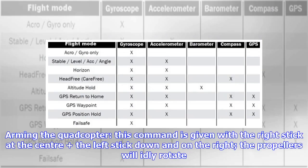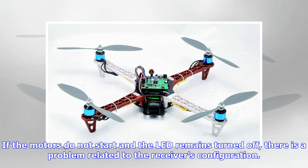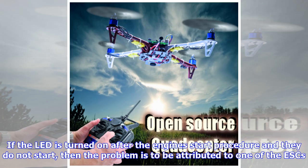Arming the quadcopter. This command is given with the right stick at the center, the left stick down, and on the right, the propellers will idly rotate. If the motors do not start and the LED remains turned off, there is a problem related to the receiver's configuration. If the LED is turned on after the engine's start procedure and they do not start, then the problem is to be attributed to one of the ESCs.